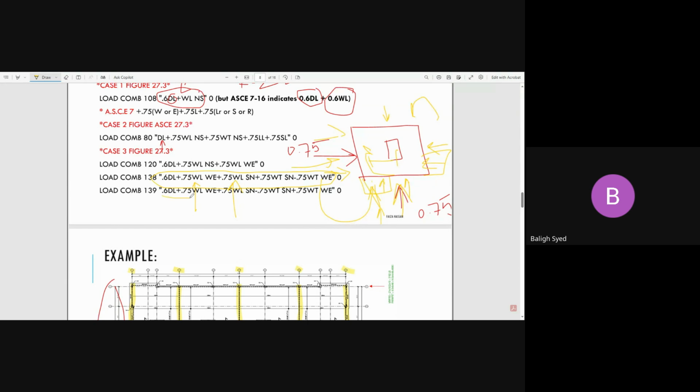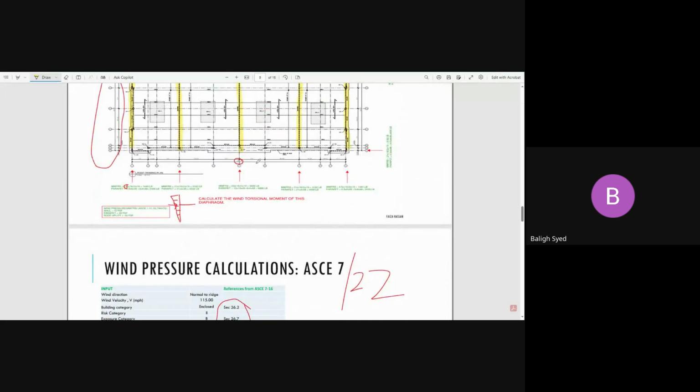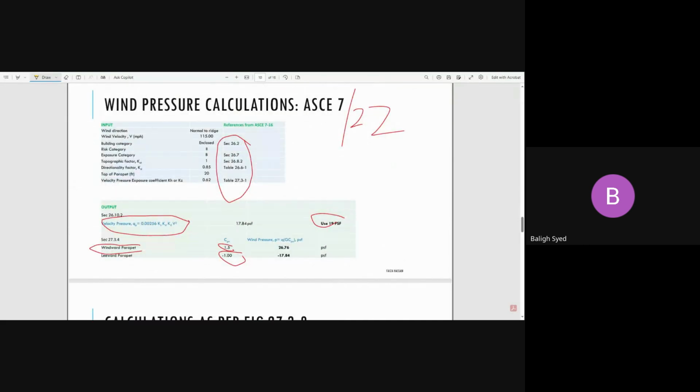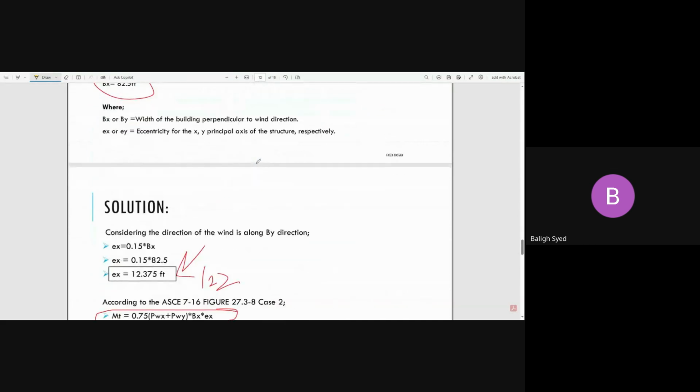This is not the intent here, to discuss all 200 load combinations, all the wind load combinations. I just wanted to touch base to give an idea. If you are interested, I'll email you the complete load matrix developed for wind loading under the understanding and influence of ASCE 7. Then you will see how one time it is added, one time it is subtracted, and it is easy. It's not that difficult.